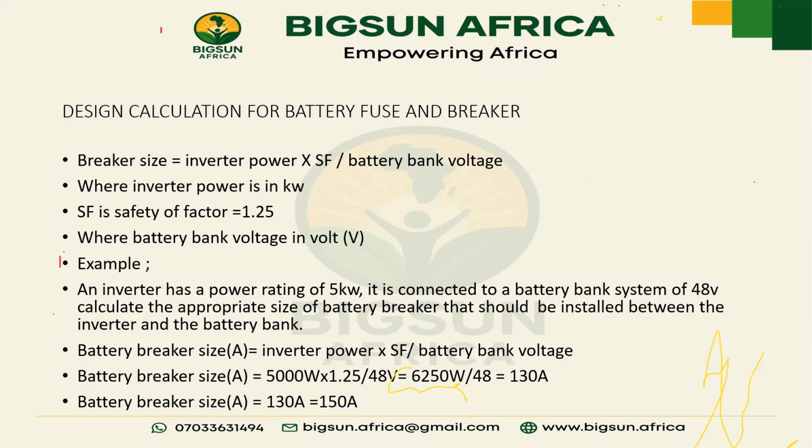So we are looking at inverter power times safety factor, all over battery bank voltage.